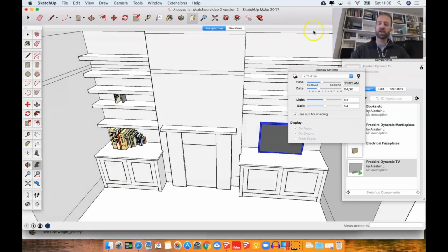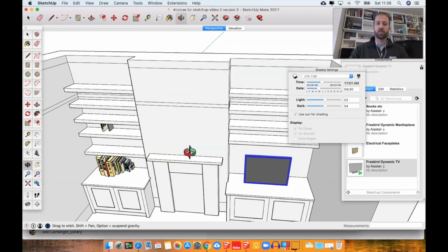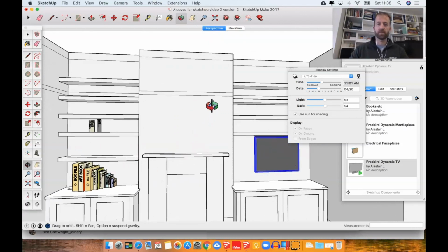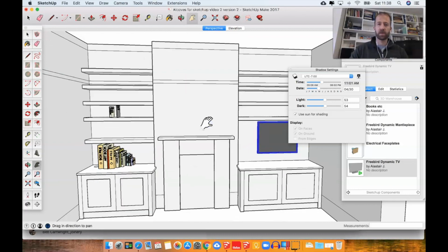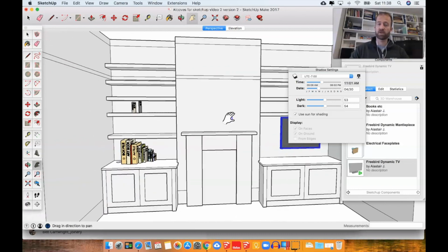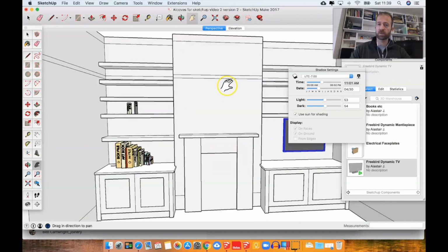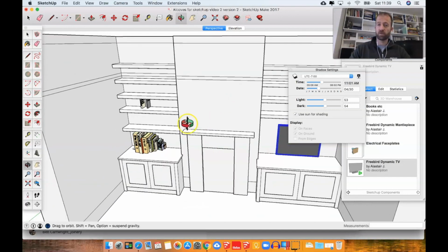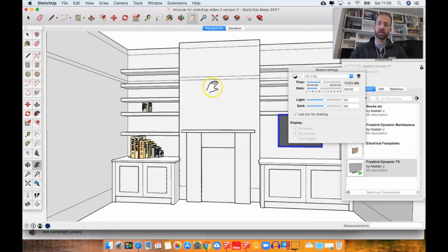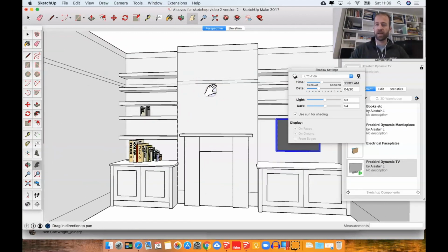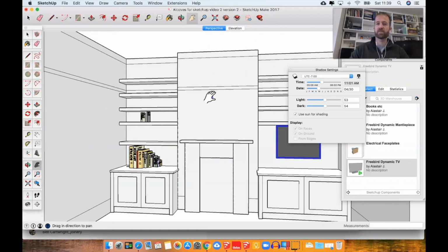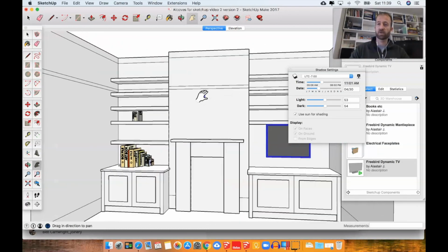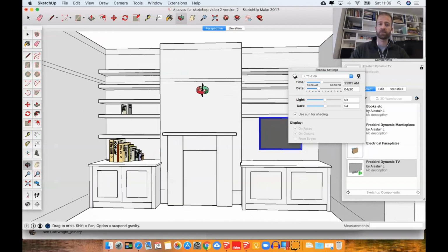Once you've made a change like that, and it's how you want it to look, it is worth then updating the scene. So we set up before these scenes at the top. There's a perspective scene. I'll just get back roughly to the camera position that I want. So I'm using my mouse for doing that. I've been using the scroll wheel to zoom in and out, holding the scroll wheel to orbit, and I typed H to get into the hand or pan tool, and then that's just the left mouse button to click, hold and drag to pan to position.